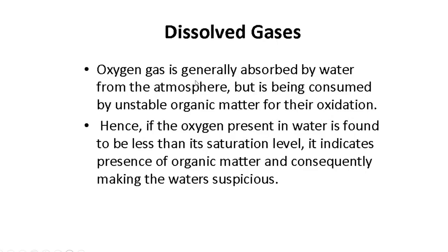Oxygen gas is generally absorbed by water from the atmosphere but is consumed by unstable organic matter for its oxidation. Hence, if the oxygen present in water is found to be less than its saturation level, it indicates the presence of organic matter and consequently makes the water suspicious to drink or use.